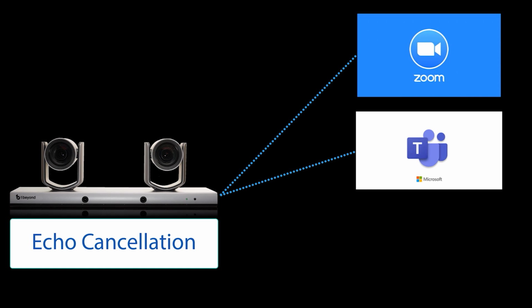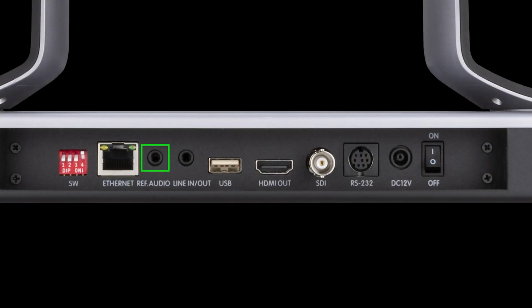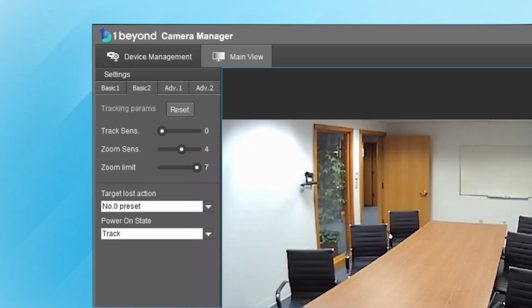Hawk can take in a mono signal from an audio source to provide far-end echo cancellation. This can be from a PC, Crestron UC engine, or DSP. Far-end audio should then be routed via the reference audio port on Hawk. Echo cancellation is required as far-end audio can produce inaccurate auto location in debug mode. This will lead to inaccurate speaker tracking. More information can be found in the product manual for Hawk.